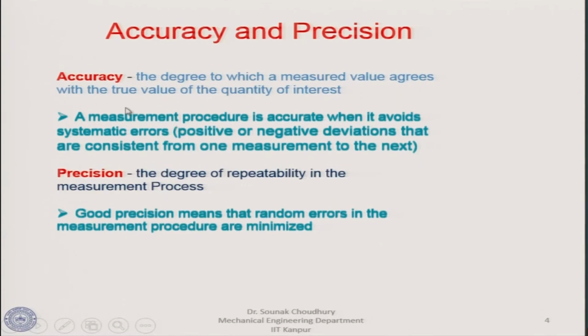I will give you an example. When we make an experiment, let us say a cutting process, you are cutting a certain length and you are measuring the force. Now, with the same parameters, with the same given input, you repeat that 3 times and see what discrepancy you get each time with respect to the other measurements.